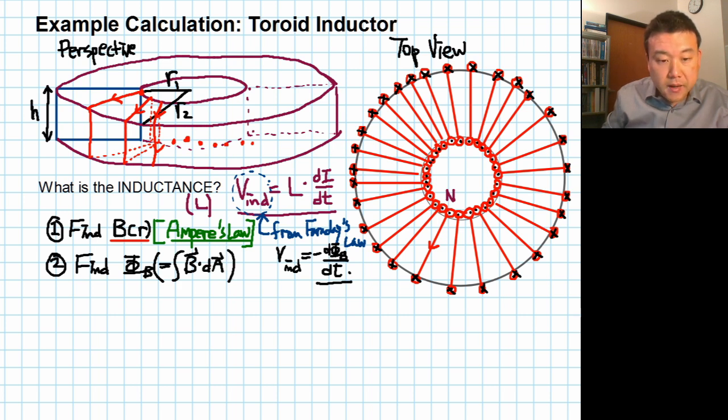And you'll find that once we find the magnetic flux, then it's an easy step from there to finish up this portion of Faraday's law, to say that the rate of change of magnetic flux is equal to induced voltage, and see if we can factor out di dt and call the remaining constant term the inductance.